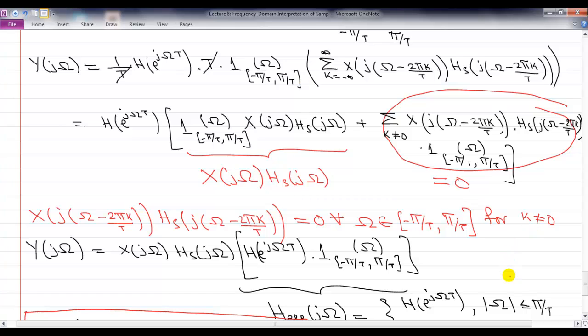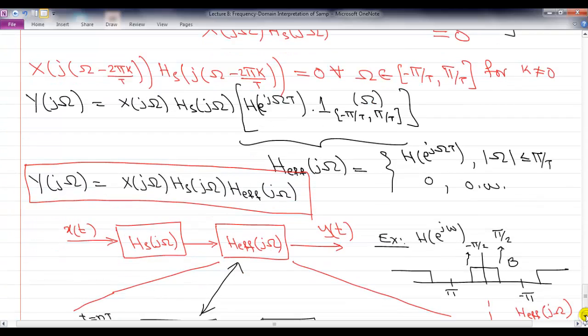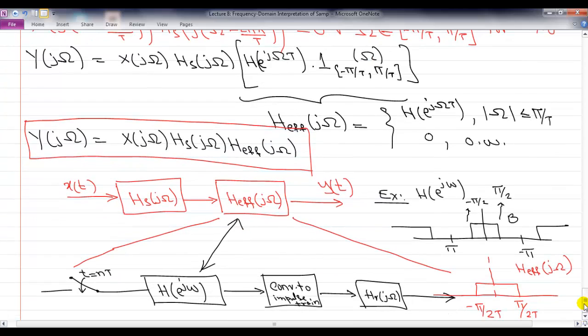But oftentimes we are willing to make the approximation that it is almost doing the same, and we just say the discrete system is just implementing a continuous time filter. And we just figure out the relationship between the frequencies of the two filters through the scaling of the frequencies.